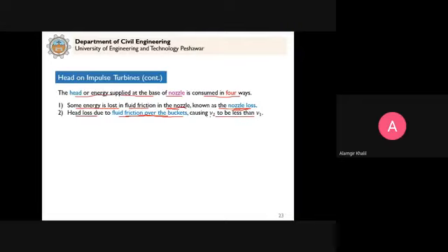That's why the outlet relative velocity, you remember small v we use for relative velocity. The same concept we will use here. The capital velocity is the velocity of the jet of water, the absolute velocity; u is the velocity of the vane or blade; and then the relative velocity is between these two, because these are moving at different velocities. So the same concept we use here. So the relative velocity at outlet will be less than the relative velocity at inlet. This will be due to the friction over the buckets.